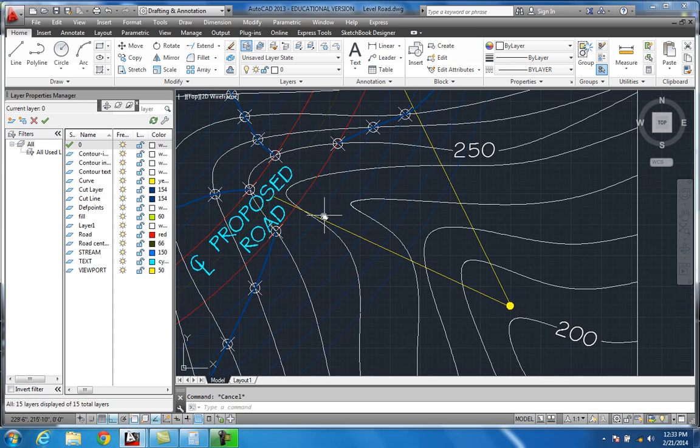But on this one, it's 2-to-1, so we use a 20-foot offset, so we can just use the same offsets we've got. But you go backwards, okay? And what I mean by that, let's go ahead and grab the fill, set it current, is like this line now will represent, instead of the 260, it's going to represent the 240. We're just going backwards.